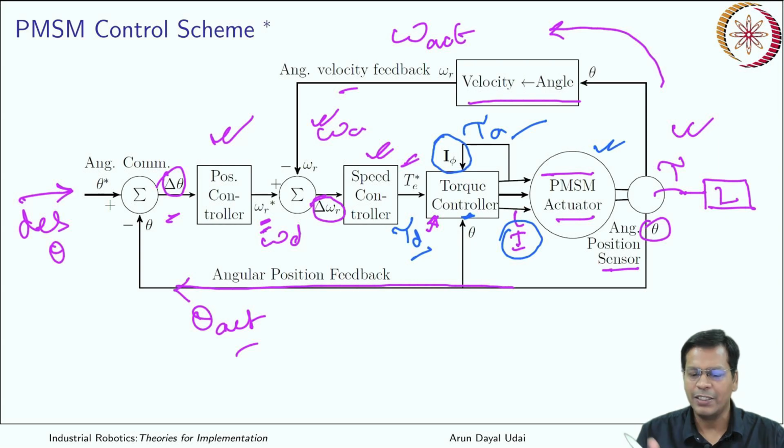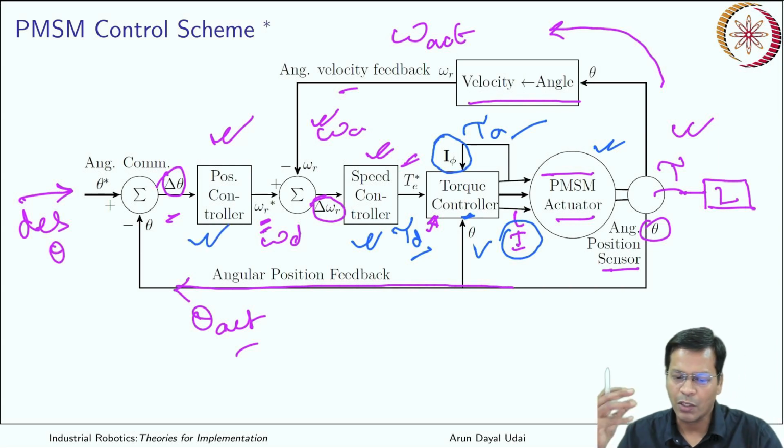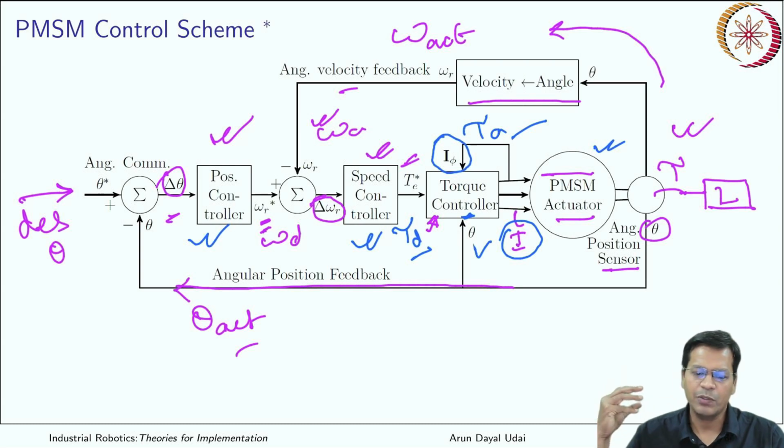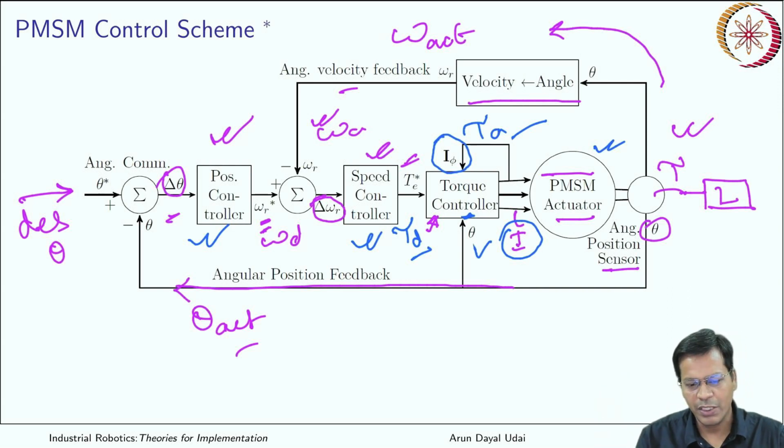So it is three independent controllers going one by one. Inside is the torque controller, the next one up is the speed, and the next one up is the position. So you are able to control the torque, the speed, and the position. Okay. Somewhere in between, you can have a desired input velocity fed in over here, instead of calculating the desired signal, directly from here.